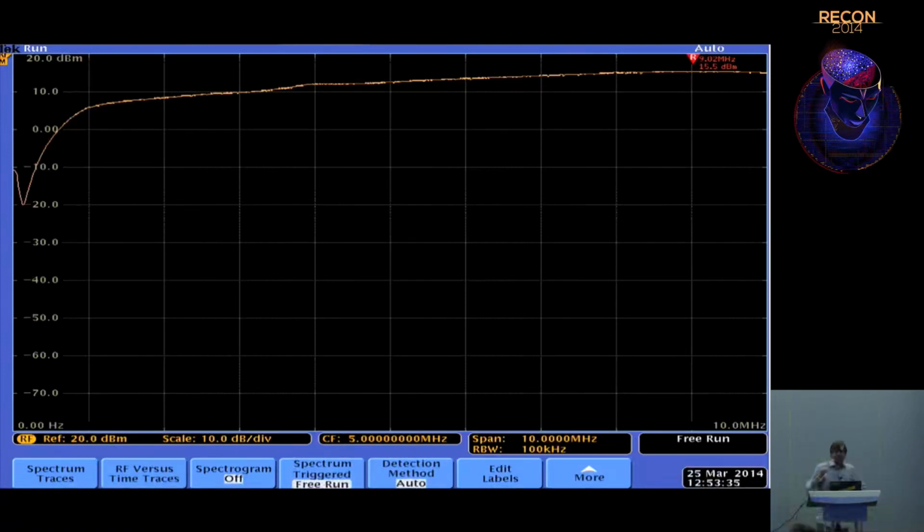And I'm probably going to have a little article in the next issue of POC or GTFO that talks about how to do that with equipment that's even simpler and lower cost than HackRF. So that's the magic piece that you need for dealing with RFID systems if you want to transmit and receive: some little active circuit that helps you take the signal that you're transmitting and use that to modulate the signal that the RFID reader is transmitting.